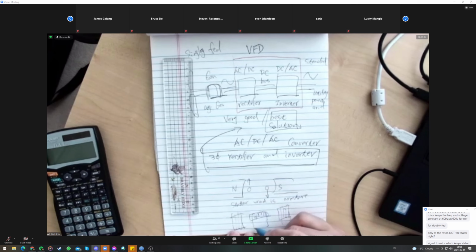We put a DC current into this rotor, because with a lower current and many turns of coil, we can create a stronger magnetic field. But because it's a low current, your commutator and those things don't need to be a big size.